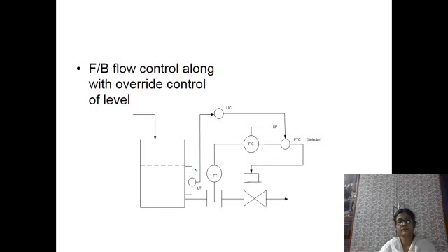So this is used for delicate systems where, due to a small change of say level or another parameter, the process plant production may get affected. For these systems, along with the existing control system, there is an overriding element for selecting the controller output in order to get a faster or quick response.